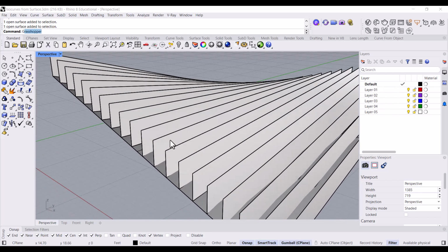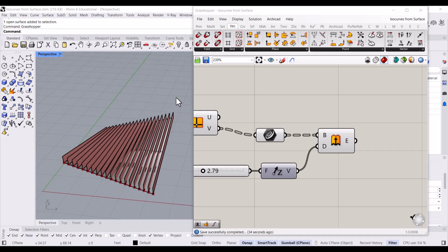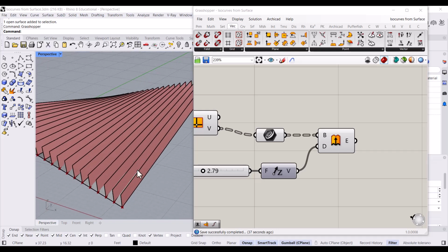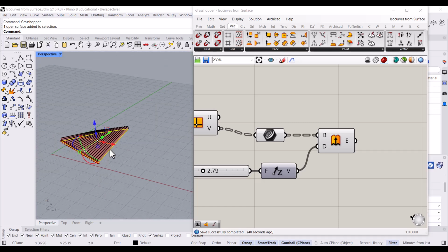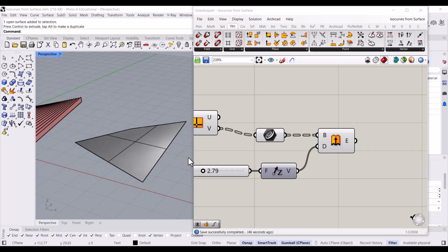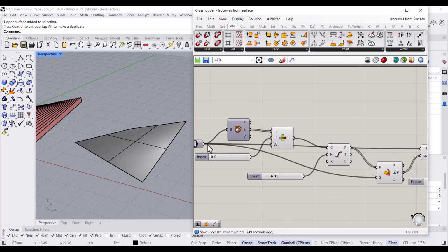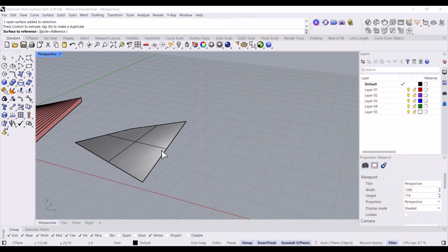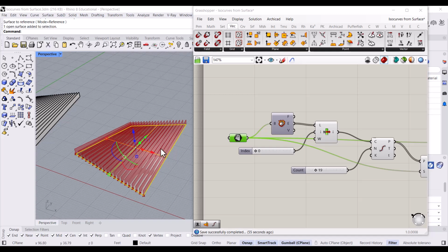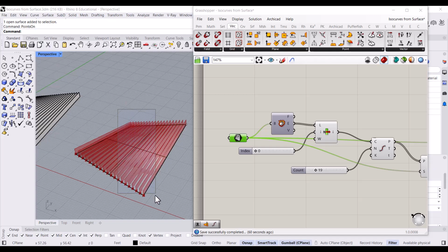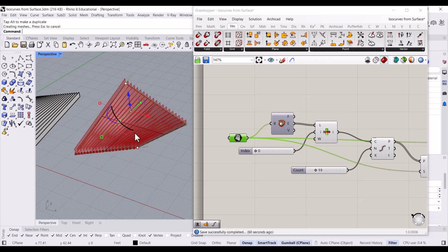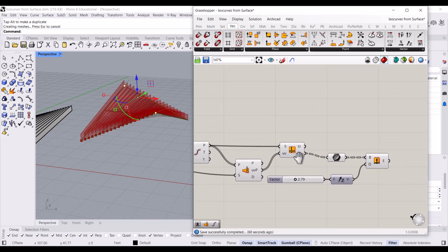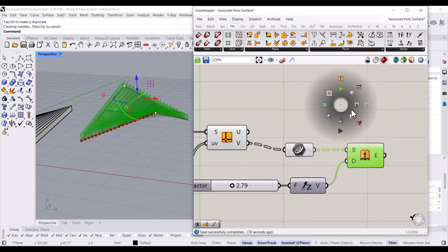And again, going back to Grasshopper, let's say I wanted to come up with a number of different versions of this design. I could select this, hold Alt and drag my gumball. I could right click on surface, set one surface, and associate it with this one. I can select it and hit points on and then manipulate each of these control points. And I could bake all of those surfaces. So I could select this, middle mouse click, bake,